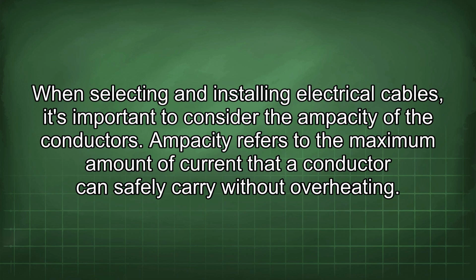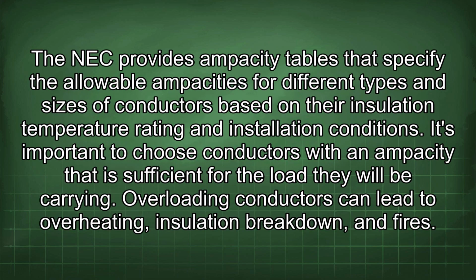When selecting and installing electrical cables, it's important to consider the ampacity of the conductors. Ampacity refers to the maximum amount of current that a conductor can safely carry without overheating. The NEC provides ampacity tables that specify the allowable ampacities for different types and sizes of conductors based on their insulation temperature rating and installation conditions. It's important to choose conductors with an ampacity that is sufficient for the load they will be carrying. Overloading conductors can lead to overheating, insulation breakdown, and fires.